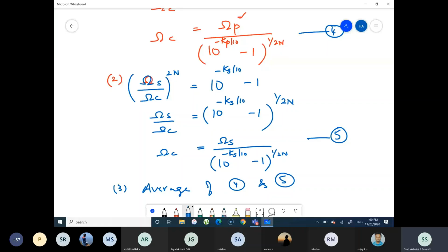These two equations that we have derived now, for capital N and omega c, are important, as they are a part of the design procedure. So far you've learned only the design of the analog low pass filter prototype, the normalized filter. If you have to convert this into other filters, you should know the transformations.